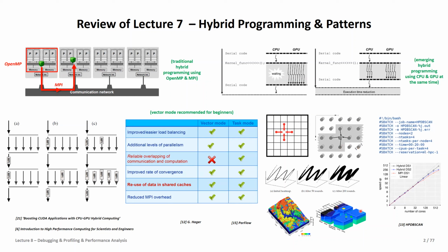However, we have also seen in advanced applications the idea of these halo regions that we had with the parallel flow model, for groundwater modeling. You crunch it up into different 3D blocks, and each of these blocks would have some artificial halo regions in order to make this kind of message exchange possible. And then you would communicate between these blocks with MPI and the halo region exchange every time step before you start the next time step. And then essentially the computing can be done with shared memory within the node, actually addressing these tiles.